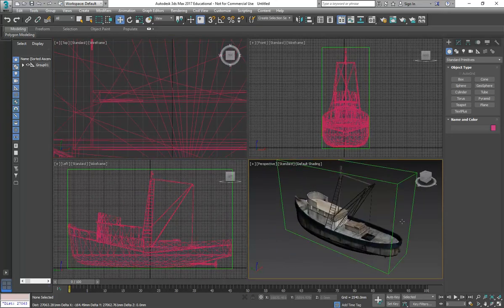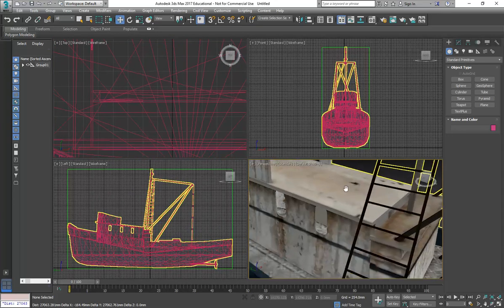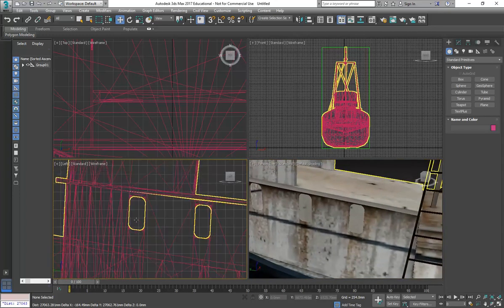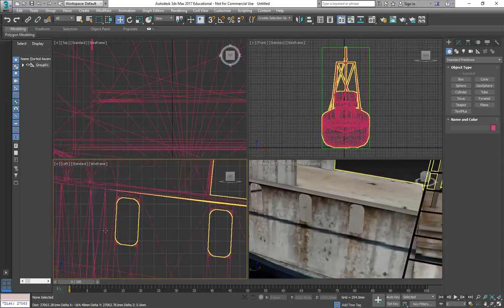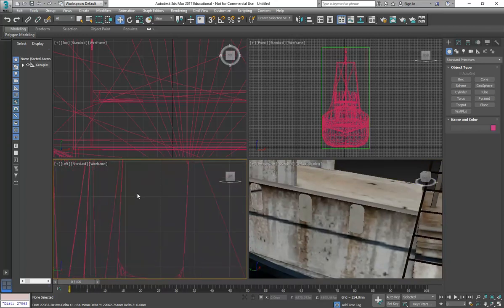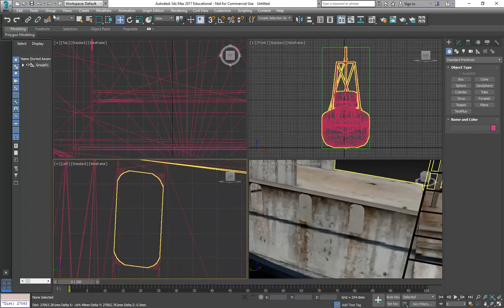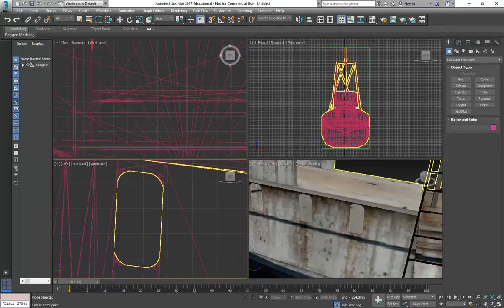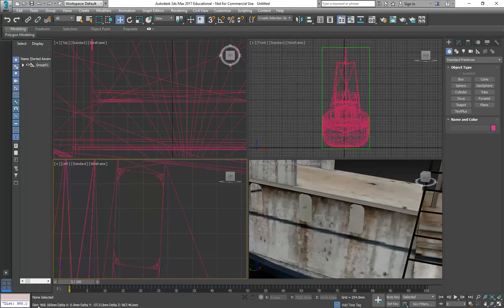Let's bring that around. Well, we've got these portholes, essentially, these windows. So maybe I'll find those in the left view and do a measure on those. So again, under Tools, Measure Distance, double click to do the first point, and then just one click to do the second point. So you can see there the height, 968, that's actually pretty good. But let's just say we wanted that to be smaller.